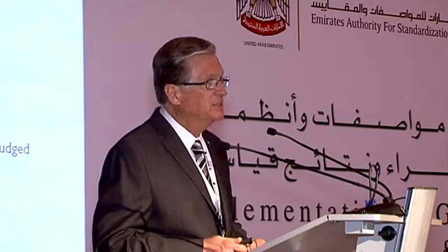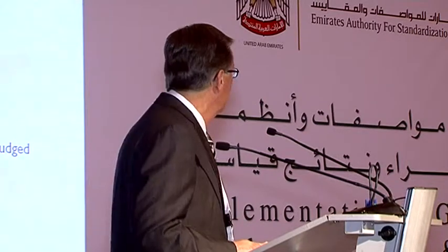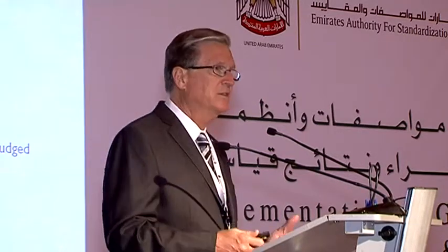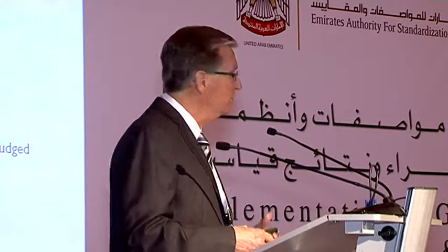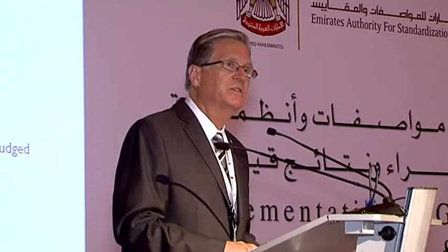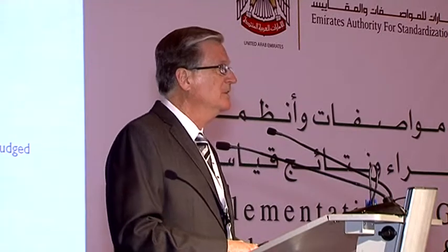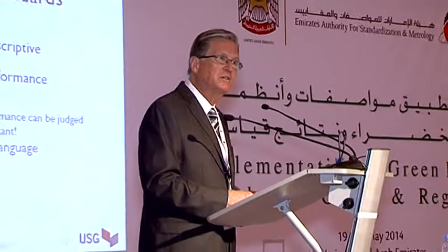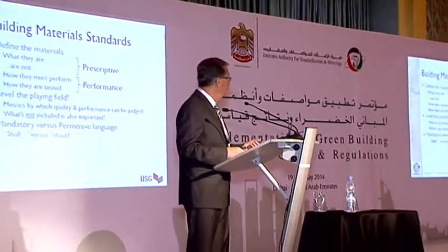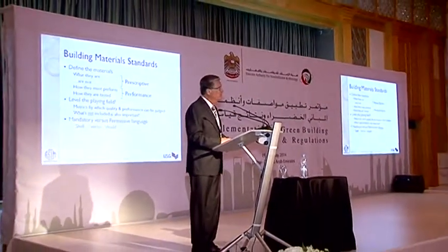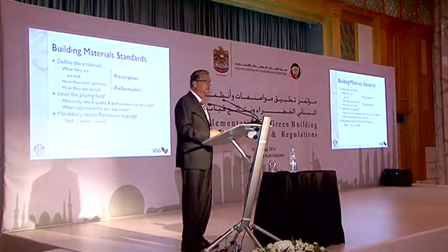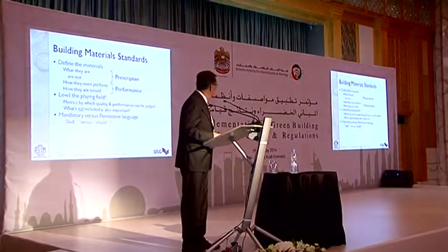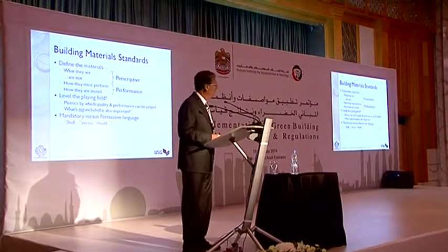Another aspect about standards used in building codes is it's important to look for mandatory versus permissive language. This is something that was brought home to us in the American code system when the model codes became very engaged with ASTM, ASHRAE, and many of the other standards developing organizations a little bit over 20 years ago, to realize that mandatory language, which very specifically states what you must have, is something which provides a measurable output.